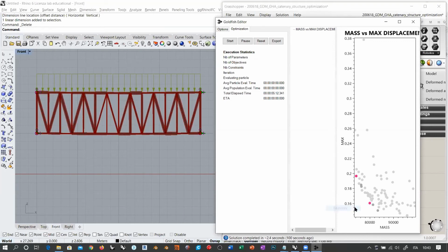This is actually producing this kind of result. You see that the vertical elements are always thinner than the others. And then if you want to optimize the deformation, you take the bottom points here, bottom right. But of course, less deformation means a thicker structure, so you have a heavier structure and therefore thicker elements.